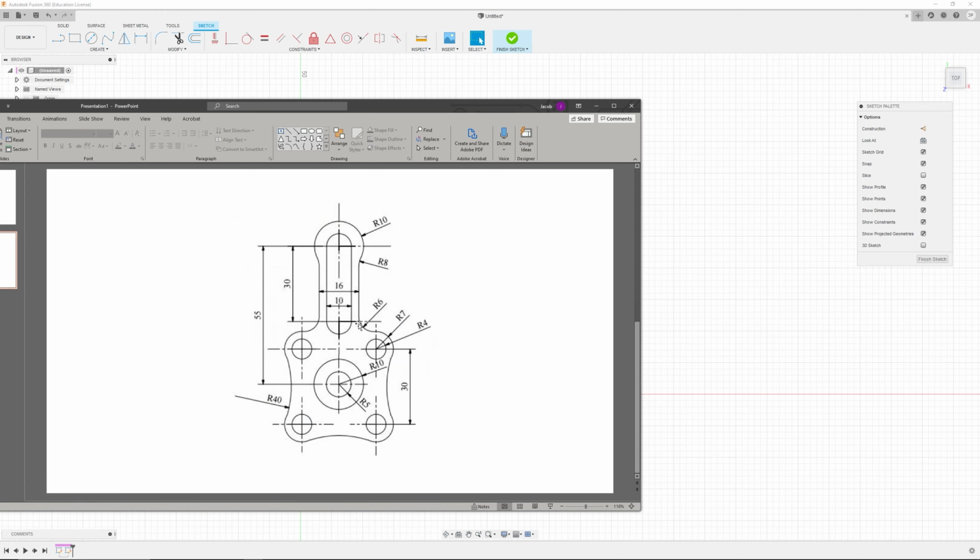So my second one here, notice how it has symmetry. It is symmetrical down the middle, and you can see that it's also got some of these lines here. Those are indicating that those are circles, and it's showing the center point of those circles, where they are relative to one another, as well as relative to the center line. So those markings there are implying those two different things, that this is a center line and that it's symmetrical relative to that, and that these are the centers of these circles.